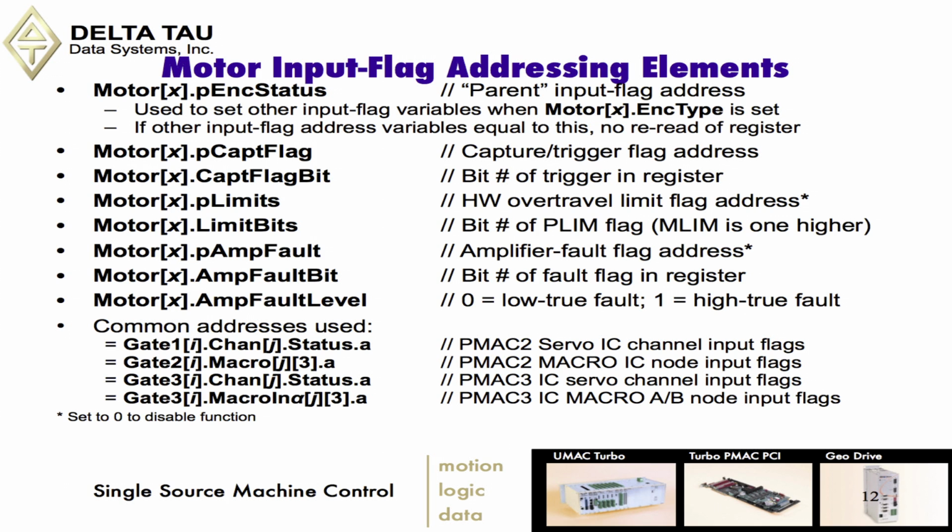Of course, it's important that the capture information come from our capture hardware if you want to use our built-in capture features. But if not, you can use software capture. We do have software capture ability in Power PMAC.